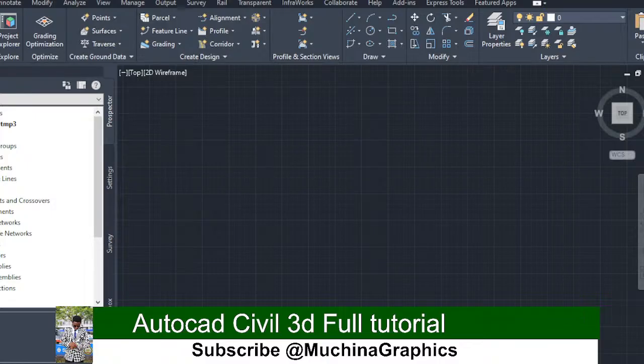So the next thing that you need to do is to know how to import your points. Now let's import survey data, the backbone of any terrain design. So what we need to do is walk through data, points from files, selecting a CSV file or text, checking the format, choosing point groups. So that is it, and we're going to import our points.